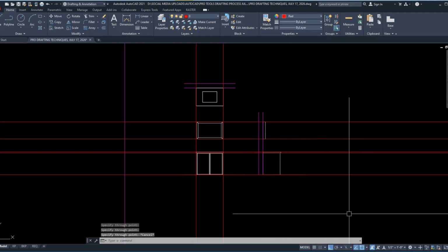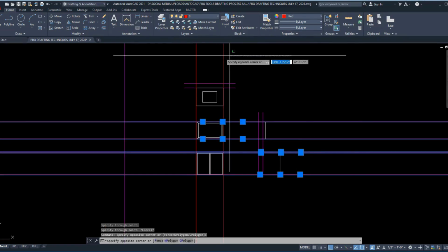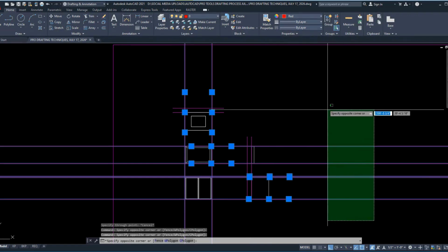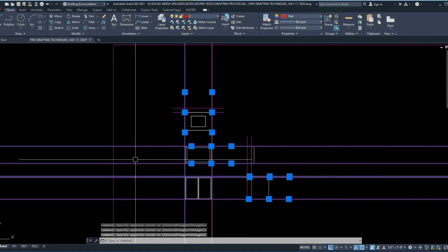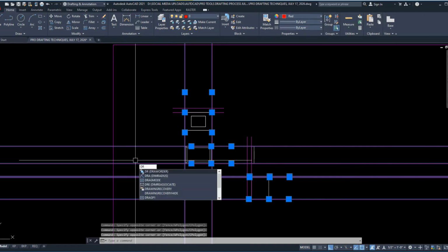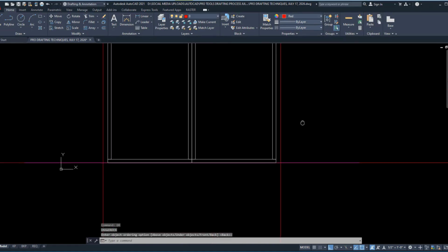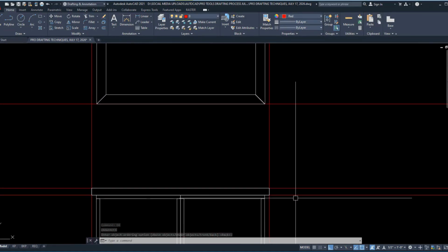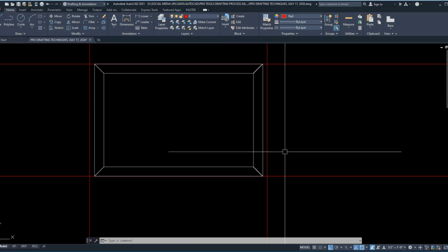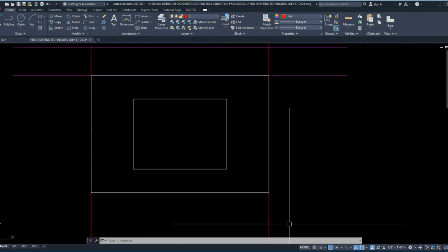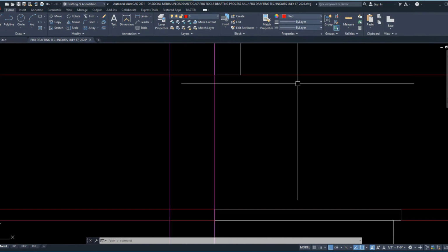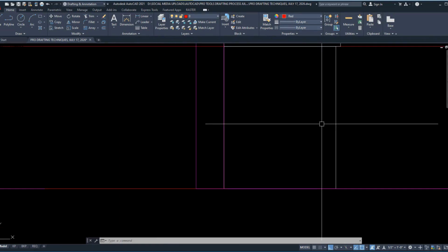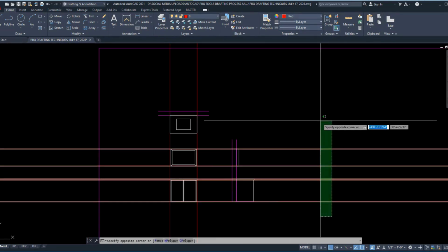Okay, now whatever lines you have dropped, just select them all together. Make a selection, blue selection, green selection in this manner on all sides of your X lines. Then simply give the command DR 2 times, enter key at the same time, and you just try to observe: are the X lines within your drawing? They should be inside of your drawing. That is when it is stated they are matching each other. So you see everywhere they are aligning with your drawing, so it's totally a fine drawing, nothing to worry.